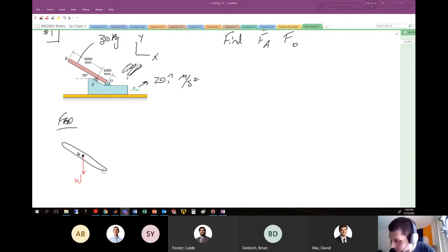So at point O down here in the bottom, we have our force at O in the y direction and a force at O in the x direction. And halfway between these two, we have this point A. Here we have a force that's acting from this roller, directed in this general fashion. By the geometry of the problem, this angle here is 60 degrees, which will help us resolve things into components. And this guy here is the force at A.